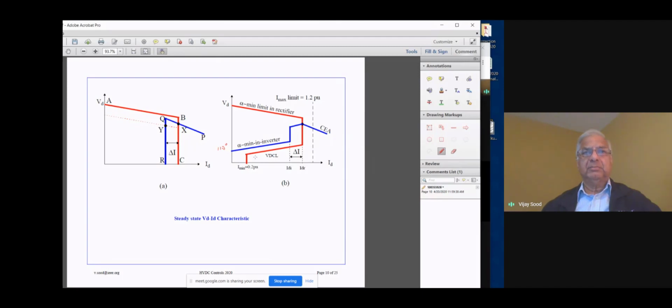And finally, we have this modification over here, which is the minimum current setting, which is typically around 0.2 per unit. This is again a minimum limit. The valves do not like having current zeros. So what happens is if the current in the DC system takes up this kind of approach, we have harmonics on the current, and we have current zeros taking place over here.